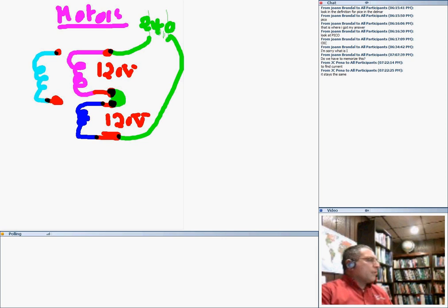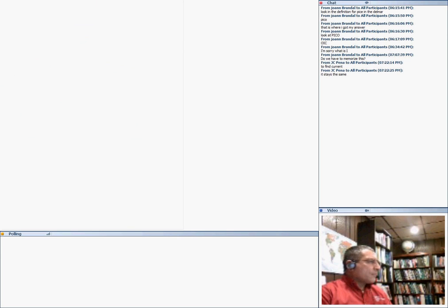I don't want to look at the third coil, as I said. Usually the third coil, they just tie it to one of these coils. That's called the starting coil. So this one, ignore it now. When you go to the motors, you understand we have a starting coil. But just look at the coil. You put the series, so you have higher voltage. So that's a very good application for series circuit, two coils in series.